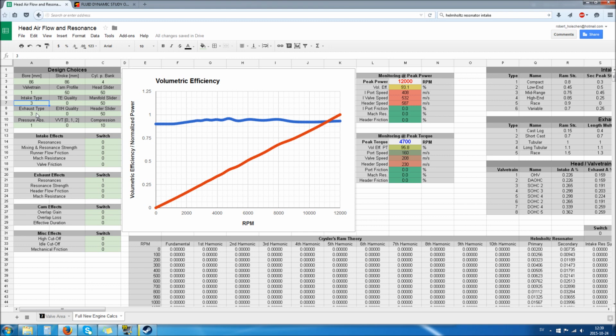And currently we have selected the exhaust type 3, which is a tubular header, the design which does something like 4 into 2 into 1, and this kind of design again moves frequencies down. This is not accurately modeled here. This is all assuming that they are gathering at the same spot, but I'm taking a few precautions here that it doesn't become too much race everywhere, by making the different exhaust resonances wider if the primary runner length, primary header length, is not equal for the different header pipes. And for the exhaust type 3, where we have a staged collection of exhaust gases, I'm just moving the whole frequency band down a bit to simulate the effect of the staged collection.